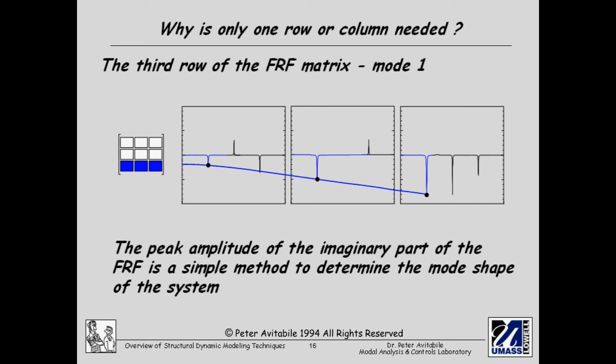And if I looked at just mode 1, just the first natural frequency, the first peak, what I'm going to see is a deformation shape that looks like the first cantilevered bending mode of that beam. So right away I get the impression that by just looking at the peak amplitude of the response, I have a sense of what the mode shape is, and I know what the frequency is because I know where the amplitude of the peak is in the frequency spectrum.